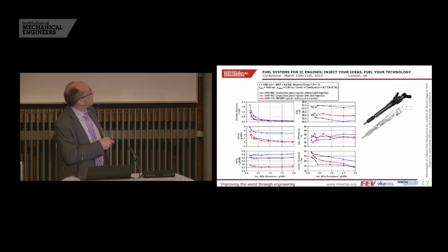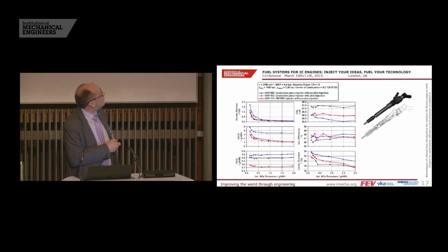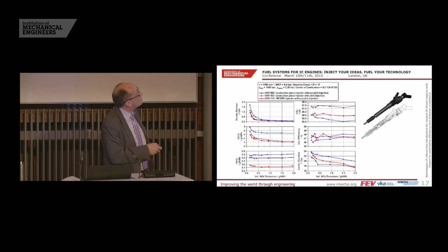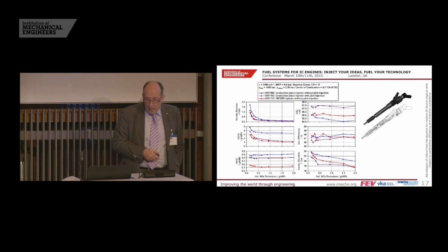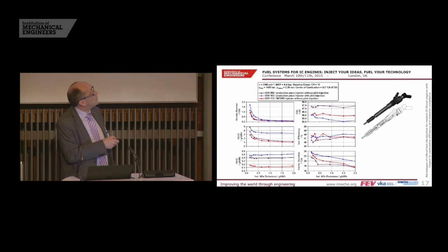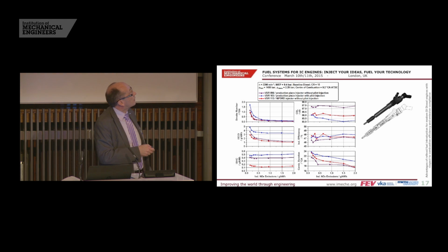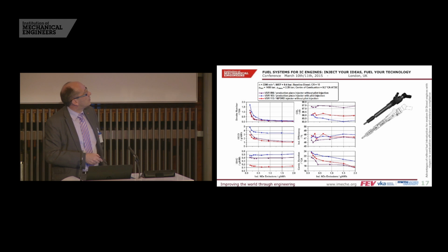On the other hand, if we look at the gaseous emissions, in terms of CO and hydrocarbon emissions, due to the quite rapid opening and closing behavior, we have benefits versus both counterparts. If we then go to the other parameters which are of high importance, like combustion noise, here indicated by the combustion sound level, we see that we are much better than the series piezo injector operated without pilot injection, and especially under high EGR rates, meaning low NOx emissions, we are more or less comparable to the situation of a piezo injector with activated pilot injection.